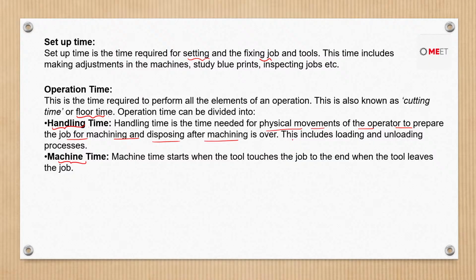So handling time is associated with the physical movement of the tools and disposing of the material or the waste which is obtained after a cutting operation. It also includes the loading and unloading process. And machine time is associated only with the period from when the tool touches the job until the tool leaves the job.